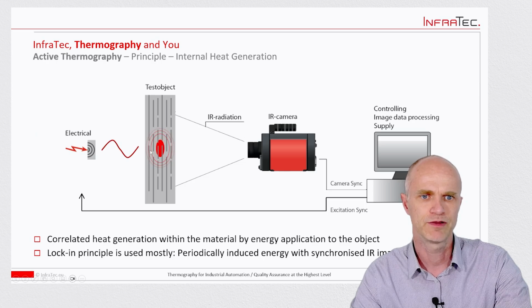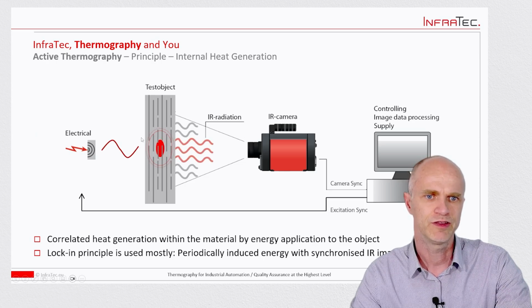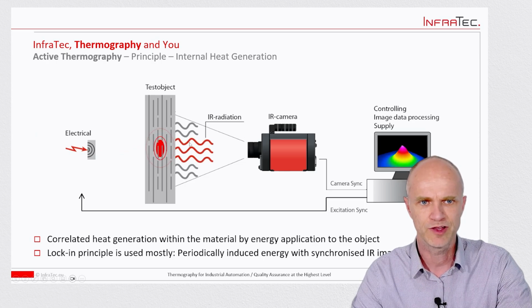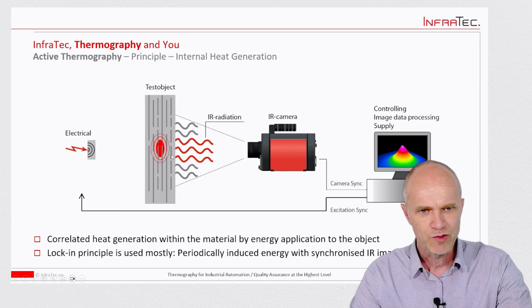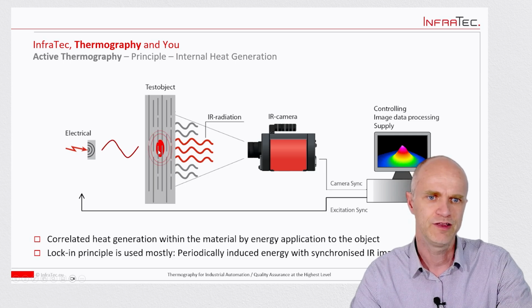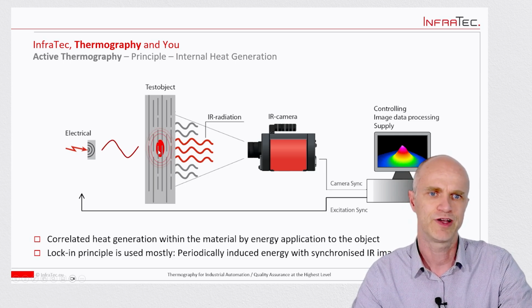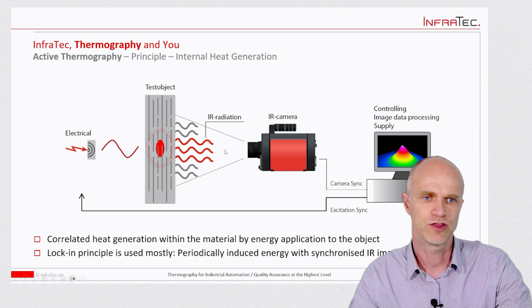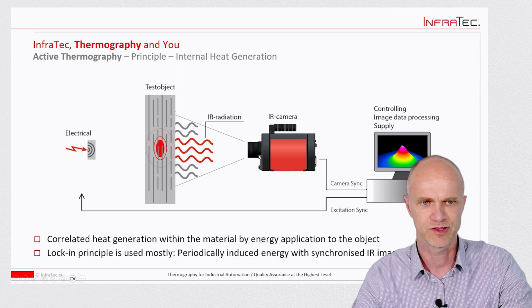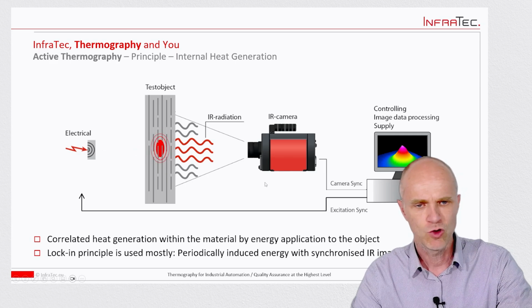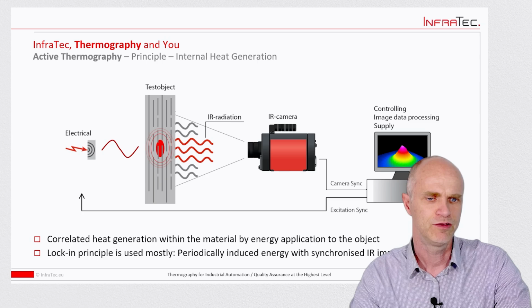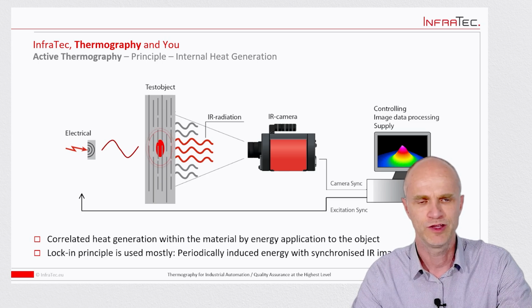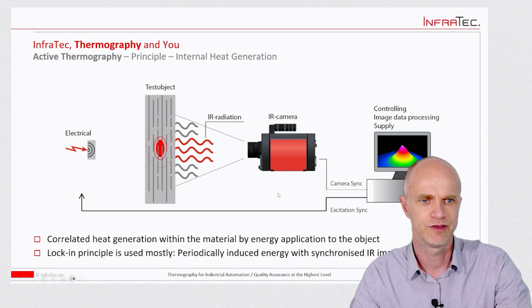And finally, if you give this signal to the component, and if there is a failure inside the sample, it will give a different heat transfer, which comes then to the surface, and it's possible for the camera to detect. Very slight temperature differences inside the object will lead to failure detection. So this makes it possible to see even below 1 millikelvin failures in the sample. And if you measure for longer times, you can even measure microkelvins.